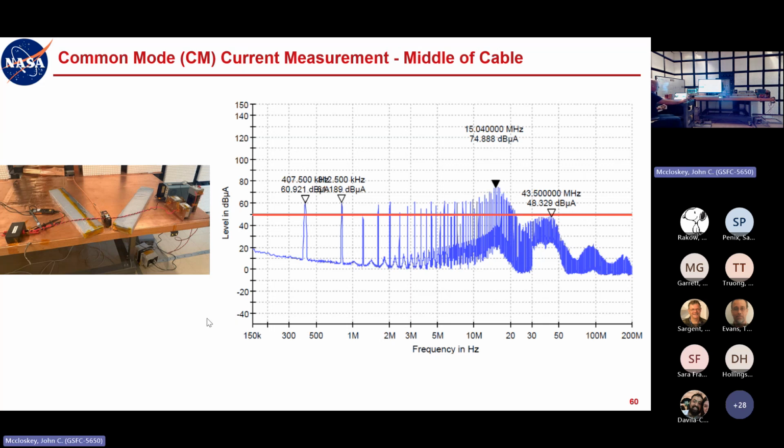Okay, so it's a mismatched transmission line, which means you are going to get standing waves, and so the level that you measure, at least at frequencies where the cable is a significant fraction of a wavelength, is not going to be constant along the length. That's really the central point. When we talk about a cable being electrically long or electrically short, it's always with respect to a wavelength. And the significance is that if it's electrically short, a very small fraction of a wavelength, you can treat it as a lumped element, which basically means that looking at how the current or voltage is wiggling in time, the entire cable is moving as a unit.